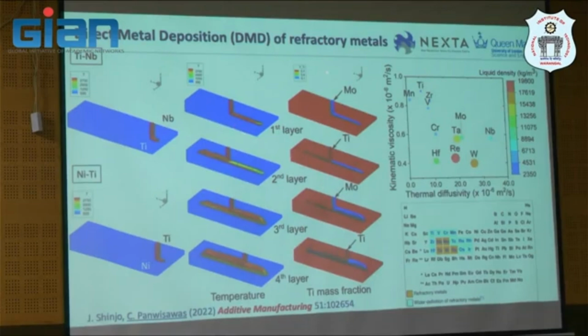So we are also doing multi-material deposition in refractory metals, and this one focuses on the application of repair. When you want to repair some high temperature rocket case or nuclear application, you may use refractory materials, like niobium, moly, tungsten, tantalum. The problem is that tungsten doesn't actually join well with the base material. So that is the inspiration for why we conducted this work.